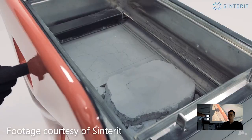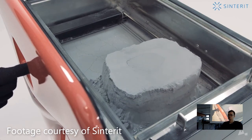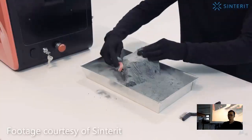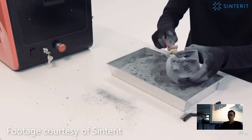You end up with a whole chamber of powder with sintered parts inside. This also means you can have many parts in the same build using a technique called 3D nesting or 3D patterning, whoever you talk to. Because you can have heaps of different parts in the same chamber, in the same build, they're not touching, they have no support material. You simply remove them at the end, dust off the loose powder you didn't sinter, and you have the final parts.